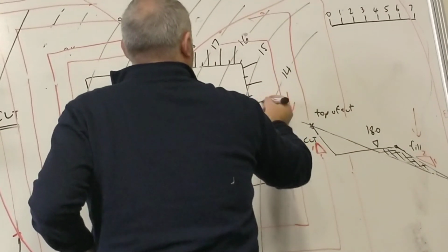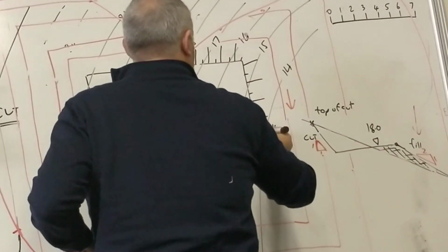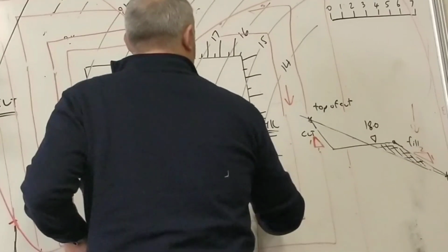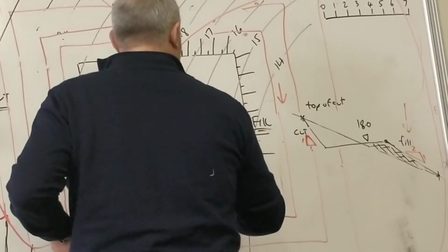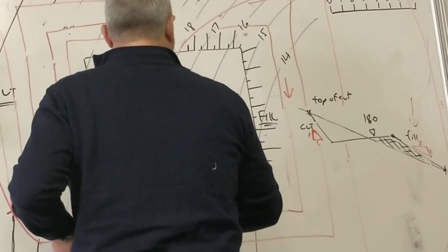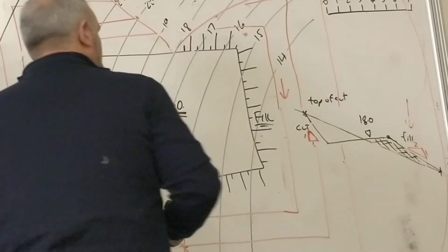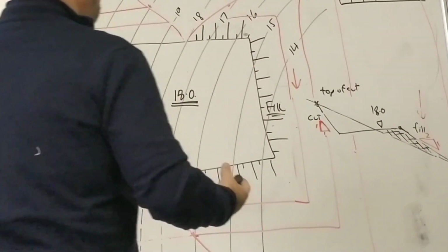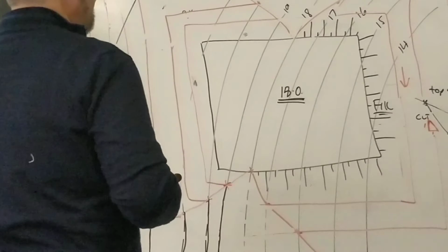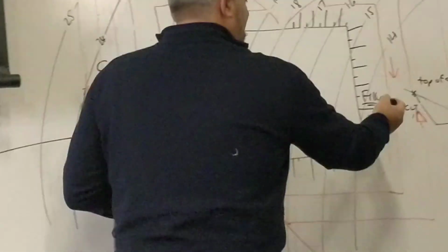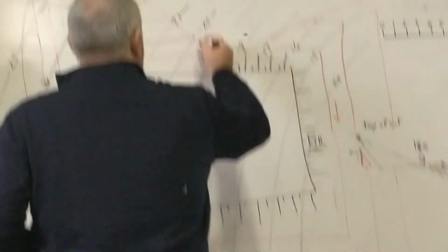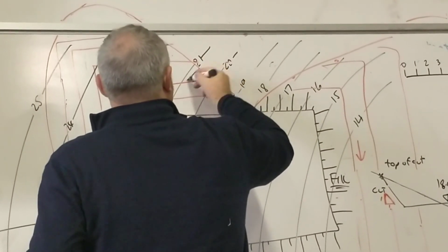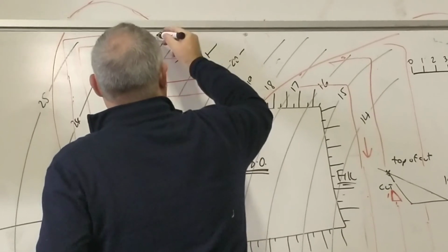Now, surveyors have got a double reason to remember this, because when you break off to do your next class, we're doing roads, and your design on the road will be quite different to this. It gets more complicated, so you're going to have to remember where the batter slope is for the fill and where it is for the cut. Now, on the cut, it is actually up here on the actual butterfly wing. So that'll be interesting when you draw that on your proposed plan.